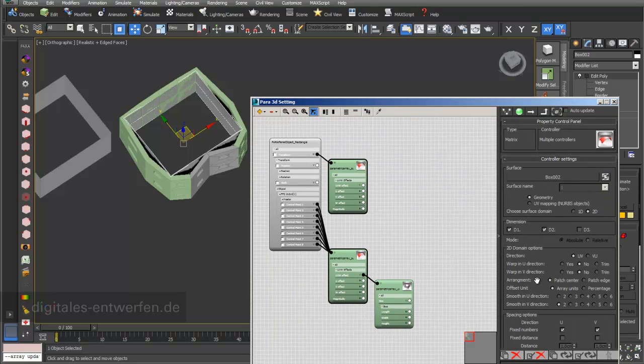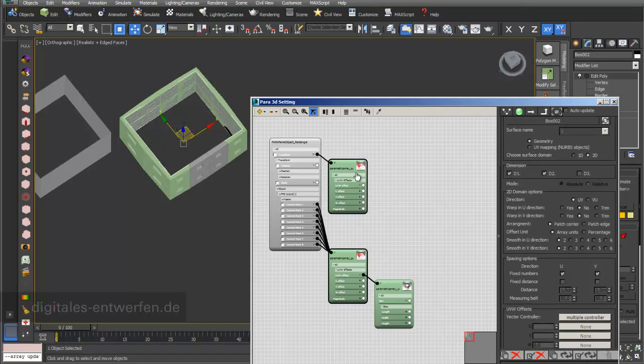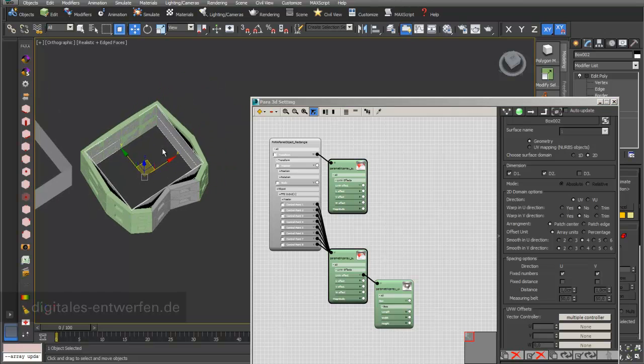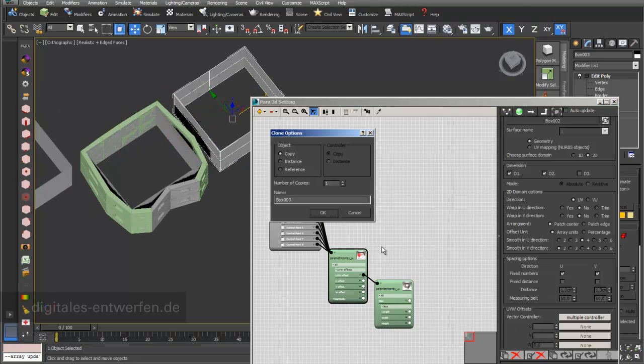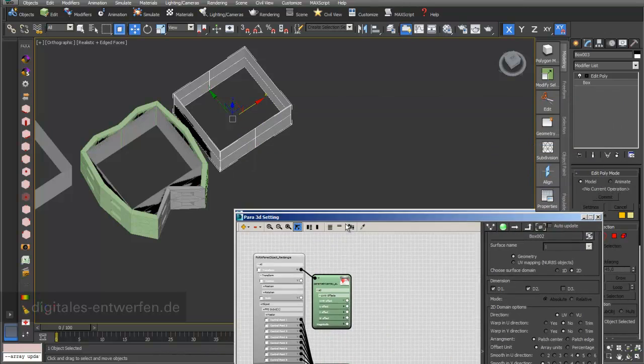And here the same thing. If I go into smooth and 2 by 2 and I auto update, then it looks pretty well. It also looks pretty well if I use 3 actually, and then we can just see that with 4 it already tries to make it round. It just works with 3, because we have 3 vertex points on one line, so it doesn't make any difference if I choose 2 or 3, just in terms of the topology. So there's already a difference, and so on. If I go and choose 4, then it also looks different like this.